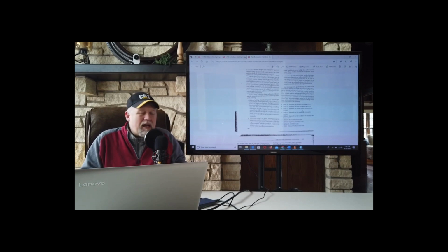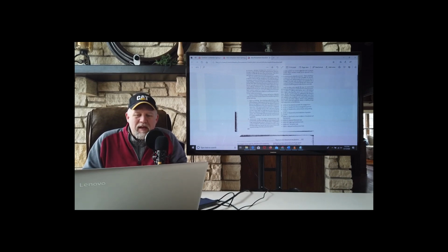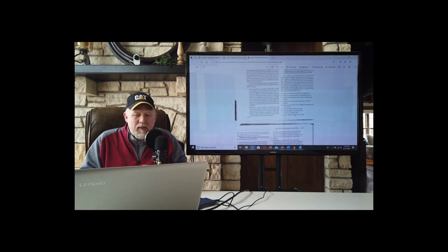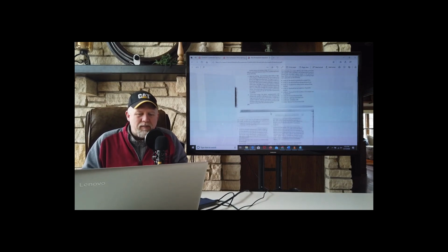Tells us things like occupancy and egress distance and travel distance and that type of thing. Conforming with NFPA 101 is one of the more difficult things that a designer is going to have to do. But other ones that are very important, NFPA 13, the standards for the installation of sprinkler systems. That is what all your fire sprinkler contractors and your mechanical designers are going to have to follow, and that is an incredibly important one as well. There's some other NFPA standards in there, but I think the most important ones are NFPA 101, NFPA 70, which is the NEC, and then NFPA 13, which is the installation of fire sprinkler systems.